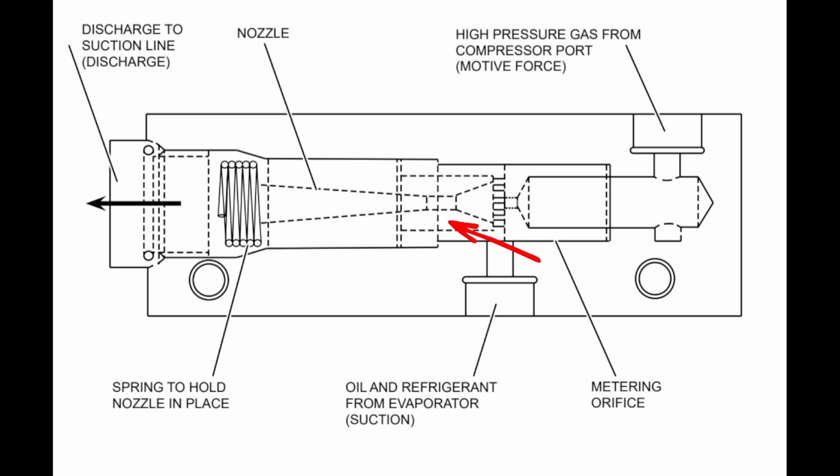oil reservoir or whether we're going to the suction of our compressor, we don't want to hit it with liquid refrigerant, which is part of what would happen here. So part of that hot gas is it helps us vaporize that liquid refrigerant as it moves out into wherever we want that oil to be.